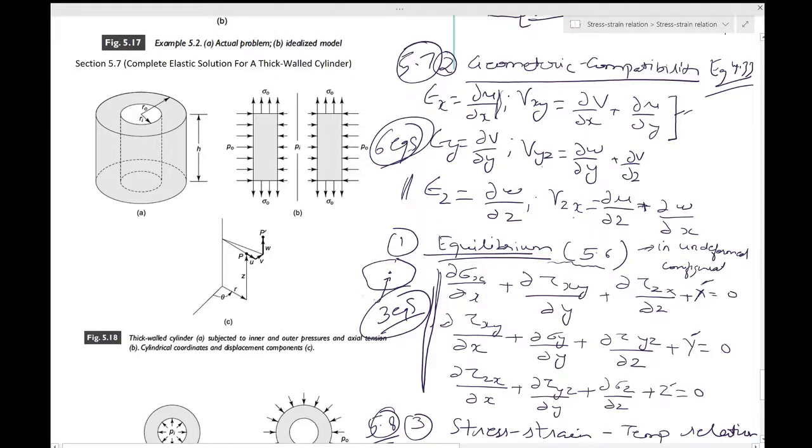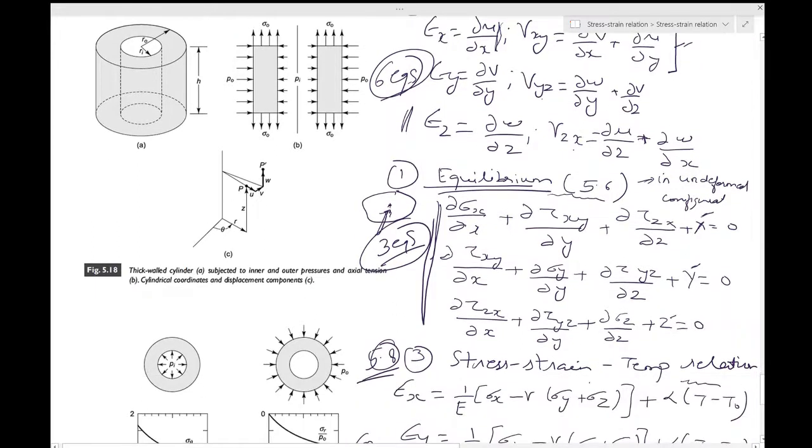So at one point these equations are defined in the undeformed configuration. This in turn means that 5.6 represents an application of equilibrium requirements in the undeformed condition. Thus the complete equations 5.6, 5.7 and 5.8, I mean 5.8 very clearly, because the strains have been found using these stresses, okay, which had these relationships in the undeformed configuration.